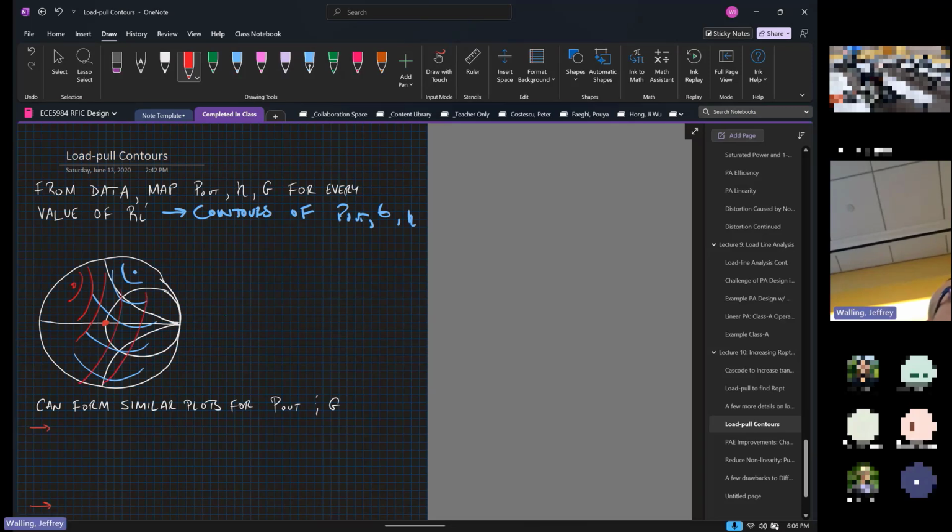Ideally, they're close to one another, though. Yeah. So for every example you showed so far there in the top half of the chart, is that because it's usually dominating the capacitance? Well, what I would say is that normally the device looks capacitive, and so you need to present some type of inductive termination to resonate out that capacitance. That's most of the time going to be the case.